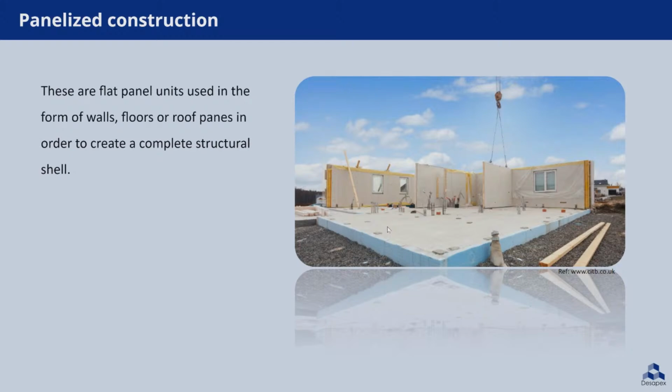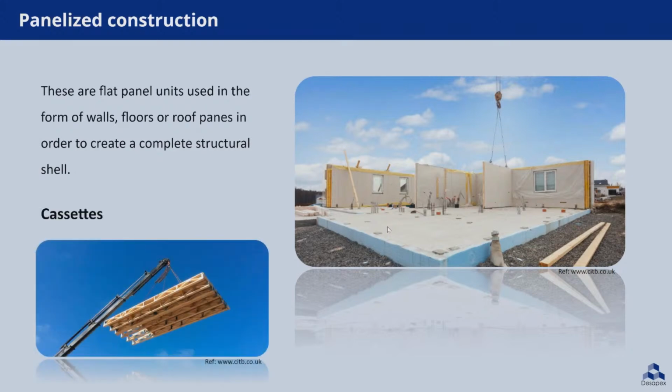Factory-made structural floors and roofs are also referred to as cassettes. These cassettes might be either load-bearing or non-load-bearing structures. These structural panel units can be constructed from wood, insulated panels, light gauge steel, concrete, or non-structural infill walls. Such panel units can be used in any style of construction. Windows, timber frames, and insulation are some examples of building components created using the panelized method.